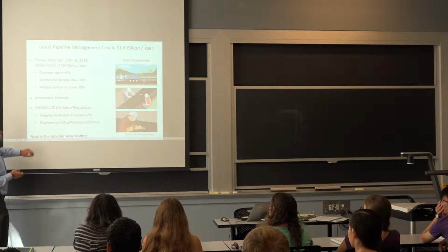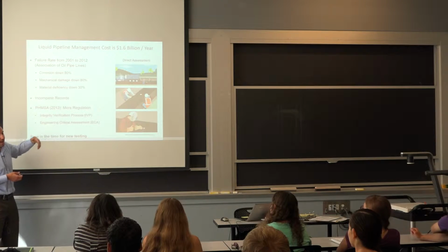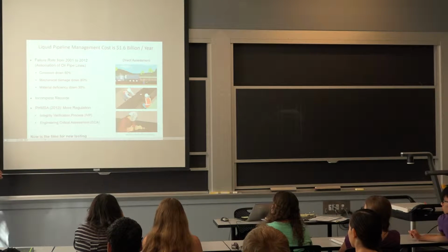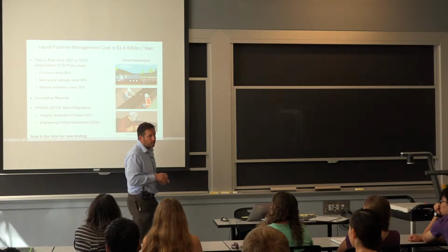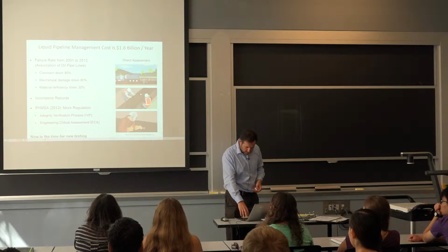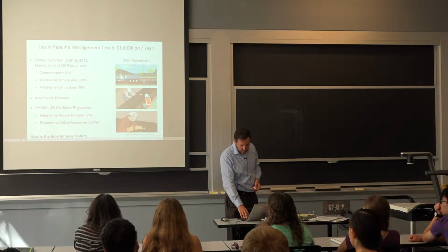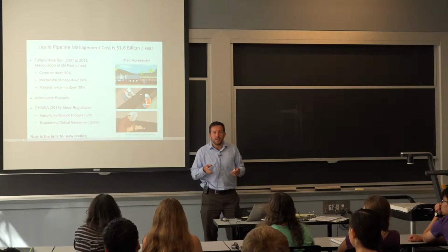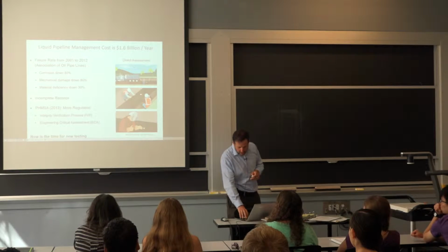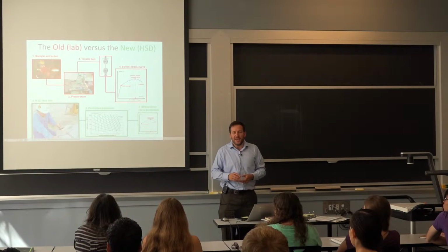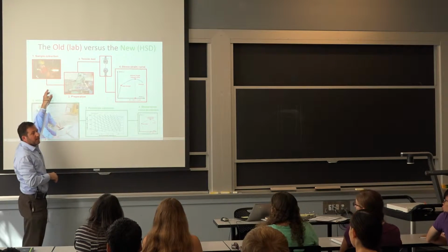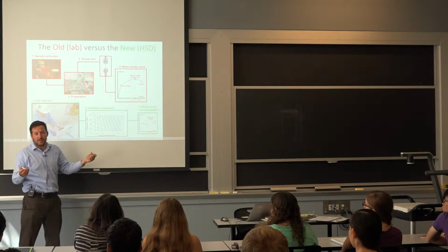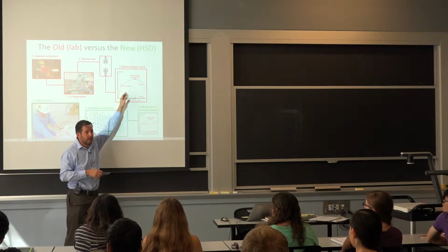And one of the problems in terms of trying to get better at having fewer failures is material deficiencies. They had an improvement, but it's not as much. And the reason is you don't know your steel unless you actually go and test it. And you'll see a lot more why I bring this up in the context of this class. You'll see that in order to learn about how the materials will behave during a tensile test. So one way to do this is to cut out a sample from the pipeline and bring it to the lab, pull on it. You get a tensile strength, you get this stress strain curve.